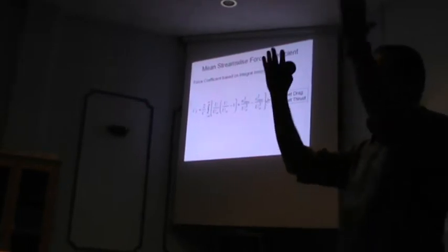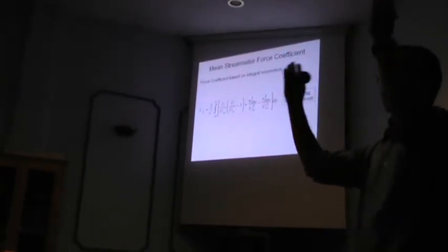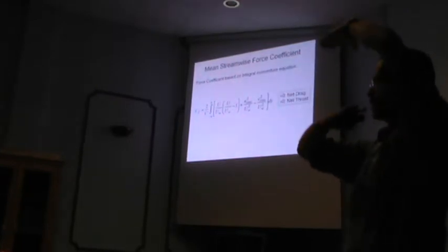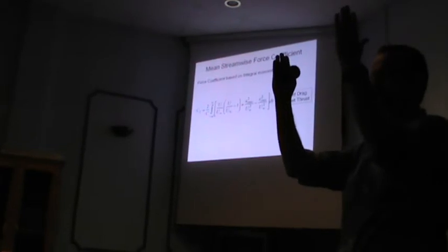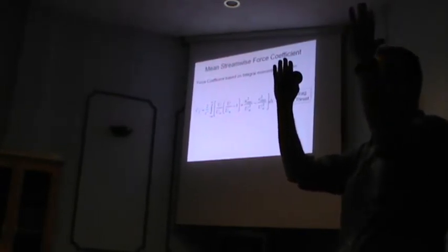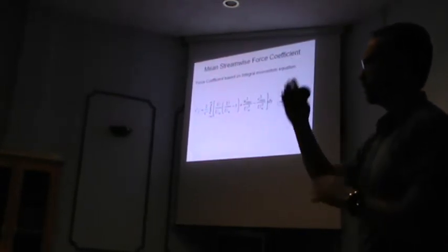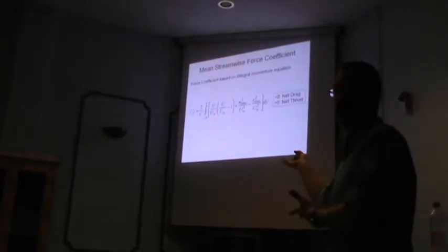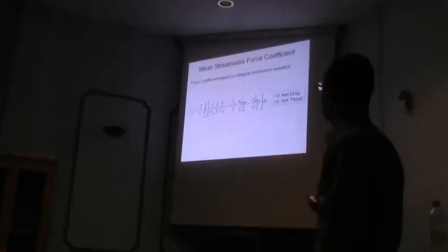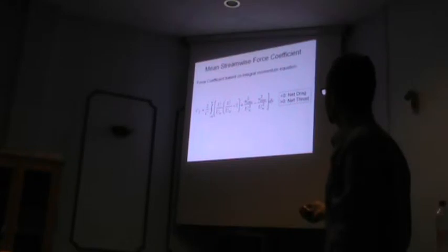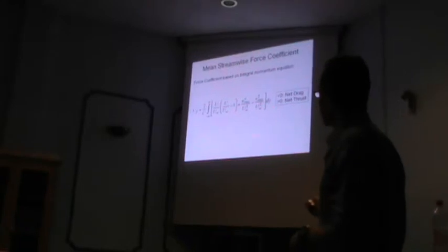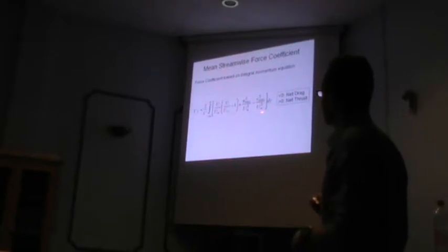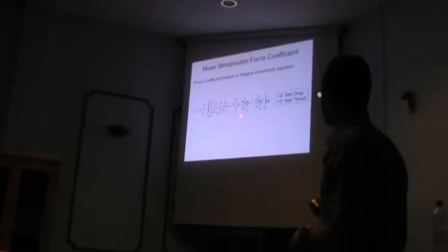It's very simple. You have the airfoil here, put a box around it. We will imagine that the top and bottom are at infinity. Then we have upstream and downstream boundaries. There's uniform flow coming from upstream, and then downstream we have whatever we can predict with the model. Now, there's something that I would like you to pay attention to here and remember for the rest of the talk. There are 3 different components in this integral that gives us CF.